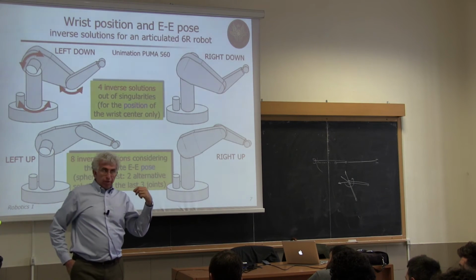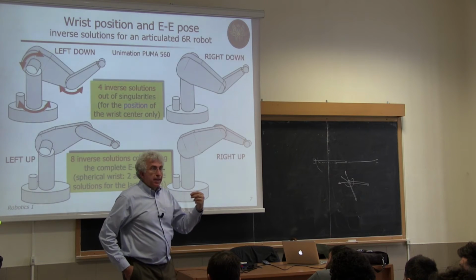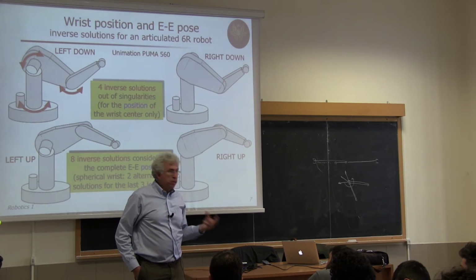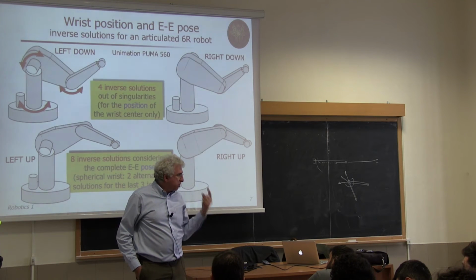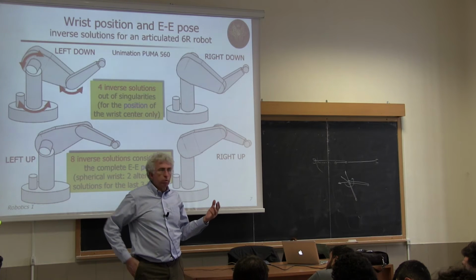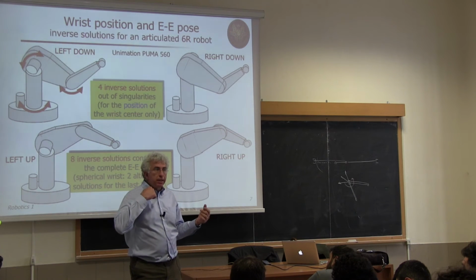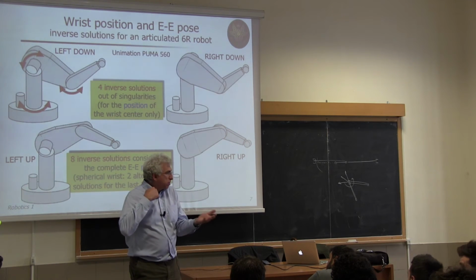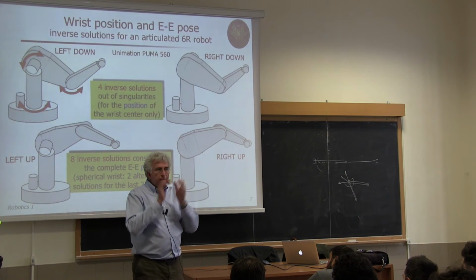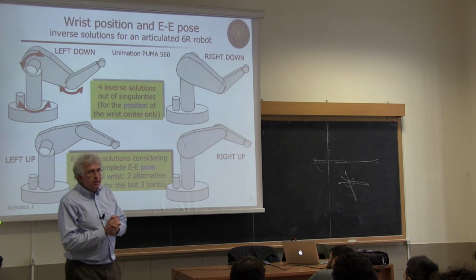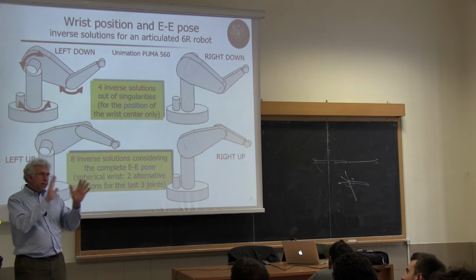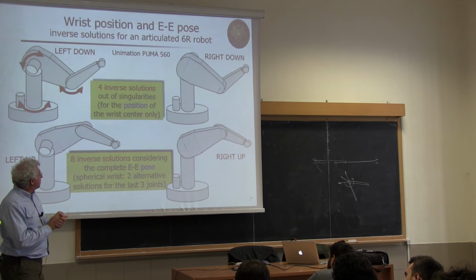And if the link lengths are equal, at the center of the primary workspace, which is also the secondary workspace, the only point, there we have infinite solutions, because we have folded the second link, so we have 180 degrees for theta 2, but then any value of theta 1 will leave the end effector at the desired position. Okay, so you have seen that even in that case, we have a multitude of inverse kinematic solutions.